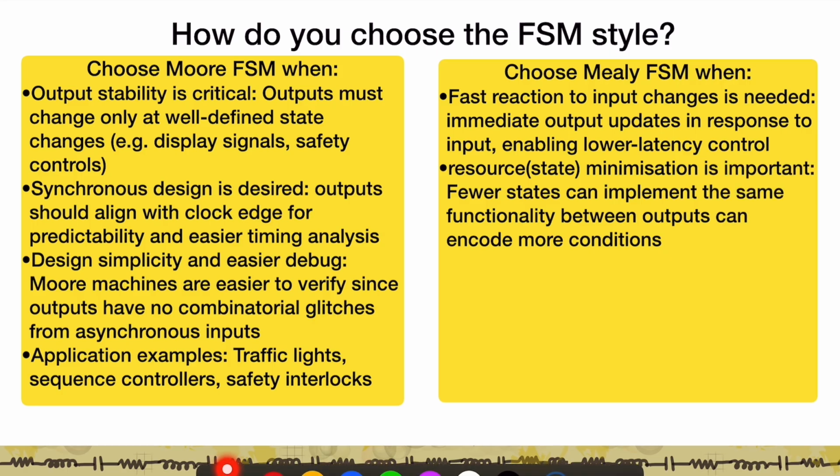And suppose state minimization is something you care about. Suppose you are building a very complex system and you don't have the luxury of building a lot of states, then Mealy typically lends itself to a lower number of states, so you can implement them with fewer logic, if you will.